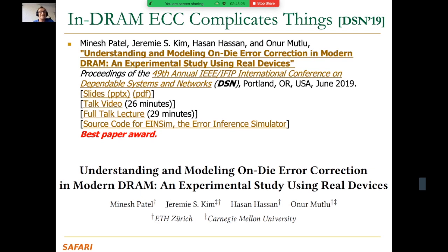And on top of that, once you add ECC, and this is very fundamental also, you add error correction code into a system, it corrects errors. There will be some errors that it cannot correct. In this case, for example, it's a single error correcting code. If there's a single error, meaning there's a single error at the granularity you're doing the correction, you can correct that bit. Now, what happens if there are double errors? If there are 2 errors at the granularity, you cannot correct that bit. What happens if there are 3 errors? You cannot correct that bit.